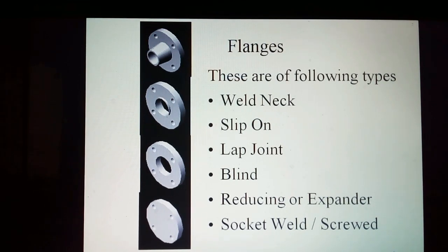This video is about pipe flanges. Flanges are used for pipe connections that can easily be opened and are of the following types: weld neck, slip-on, lap joint, blind, reducing or expander, and socket weld or screwed.